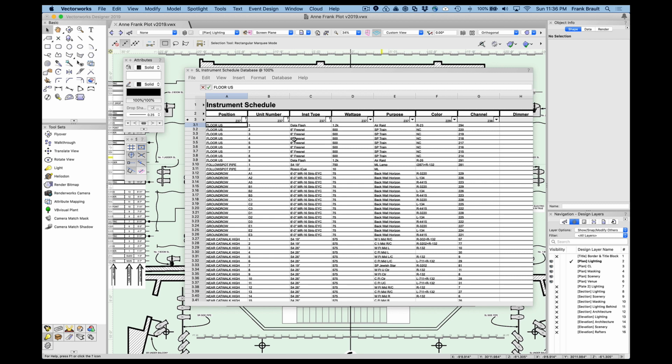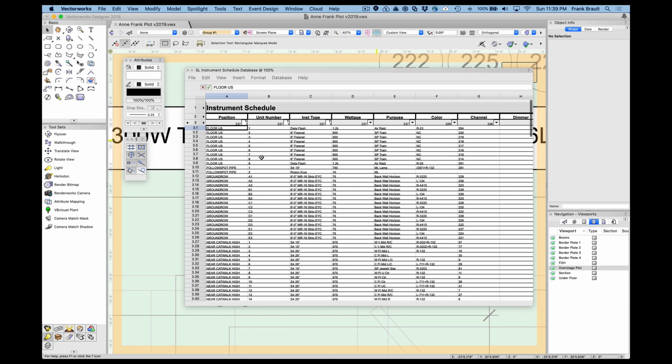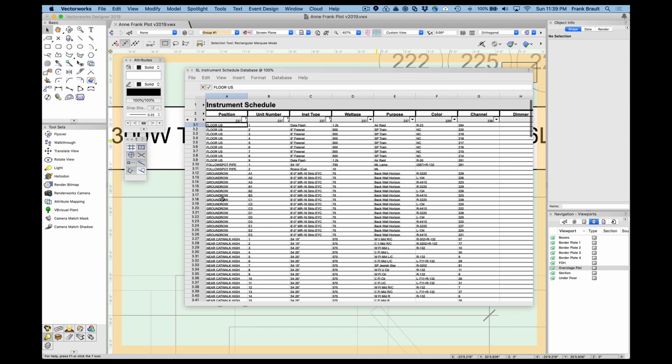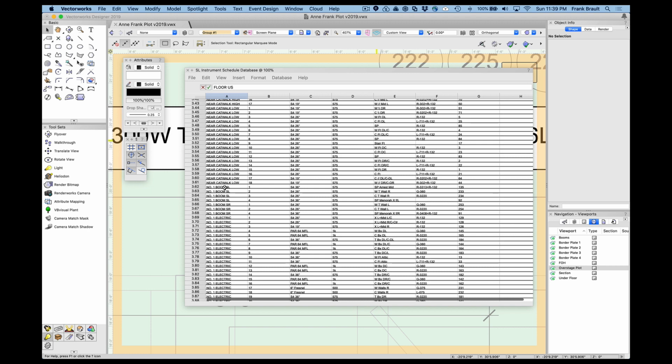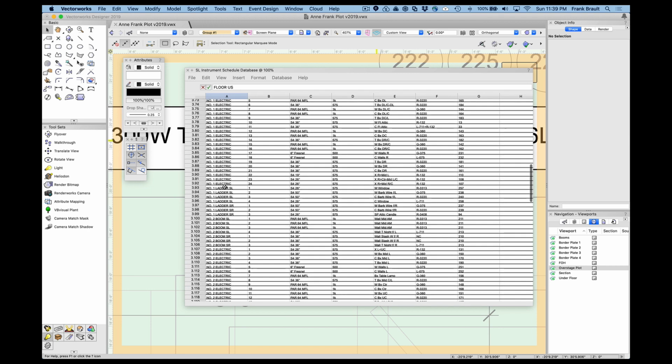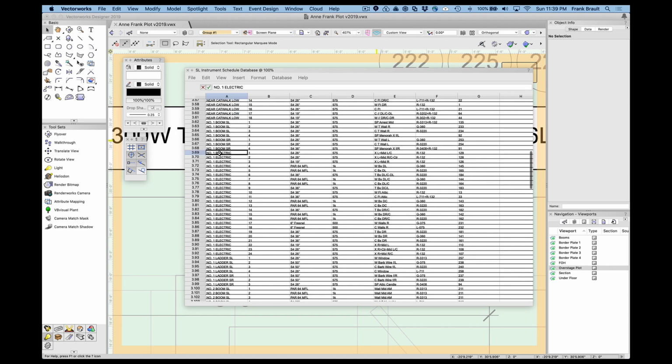Now, let's look at worksheets as an example of Vectorworks' relational database power to present non-graphical data that has been extracted from the model. This represents an important capability which is built into Vectorworks. You can process non-graphical information such as channel, color, any information, including takeoff and linear quantities, as well as areas and volumes that are part of the model.